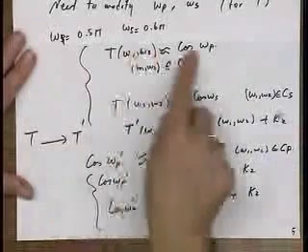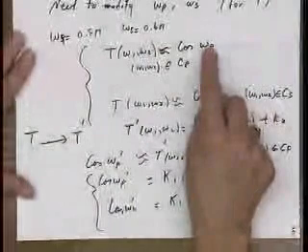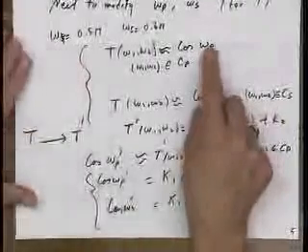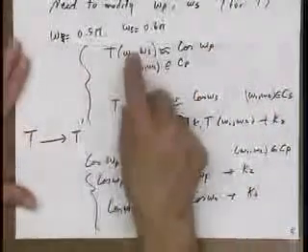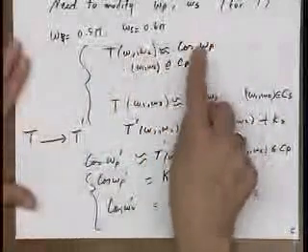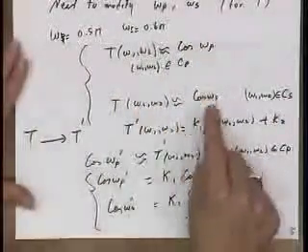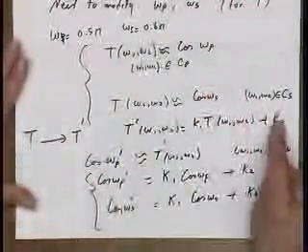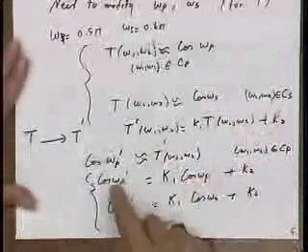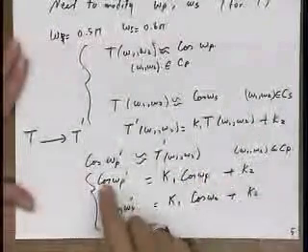Right? Because already we had ensured that we had picked some omega p and omega s out of the hat. It was 0.5 and 0.6, and we knew it's not going to be our final choice. But using that 0.5 and 0.6, we designed the t. So that t that we designed, its contour on C sub p approximates cosine omega p, and its contour on C sub s approximates cosine omega s. So now that we change t to t prime using this relationship, the contours of the new transformation correspond to cosine omega p prime, and omega p prime is just the old omega p modified by this to get the new one. Is that clear to everyone?